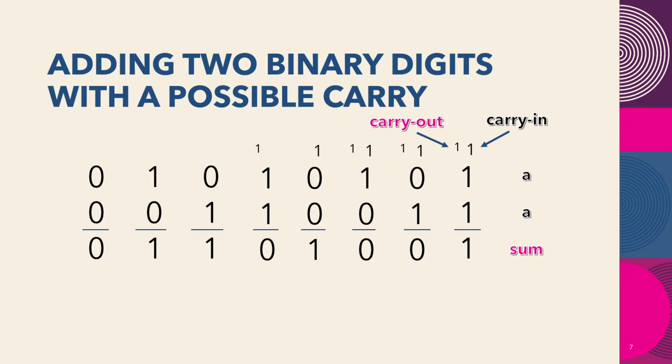These big number 1s above the columns represent another input, a 3rd input, which is the carry in. And for the outputs, we have the sum, which is the number at the bottom of each one of these, and the carry out, whether there's a carry out from the operation for each one of these columns.